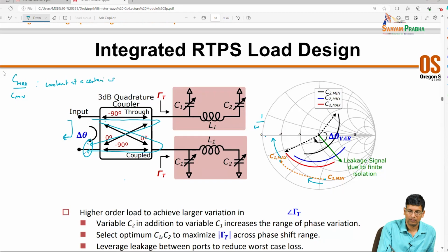What I'm asking is, can we remove the varactor itself and replace it with the open and the short? But then you will only get two states. What about the other states? And when you replace it with the open or short, in order to get a good short, you want this R to be small, so you'll put a big switch. And when you put the big switch, that switch will have a C off capacitance. So you'll again not be at an open, you'll be somewhere here in the Smith chart. And that will only give you two states.